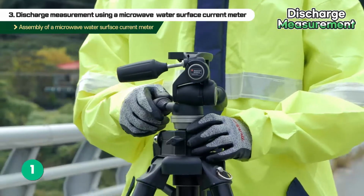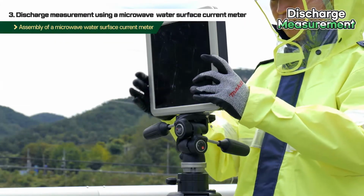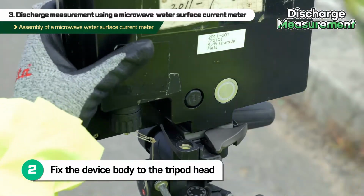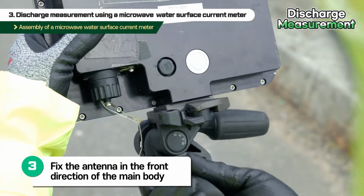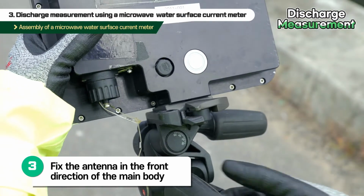To install the microwave water surface current meter, first an adapter is mounted on the tripod head, and then tripod head is assembled. After adjusting the height of the tripod, the body of the microwave water surface current meter is fixed to the tripod head. The direction of the antenna is made to face the front of the body, and the 3 axes of the tripod head are also fixed.